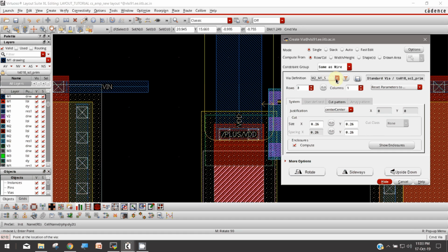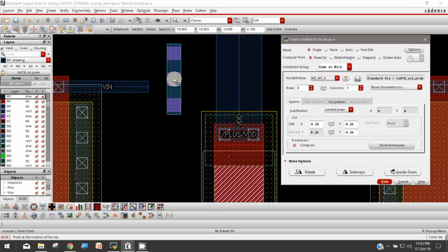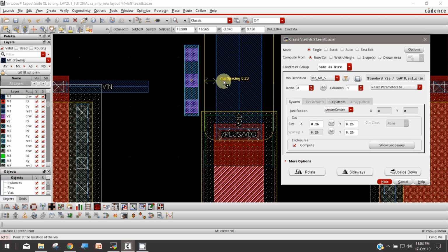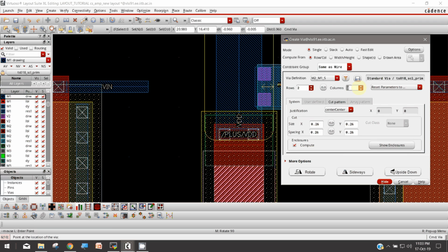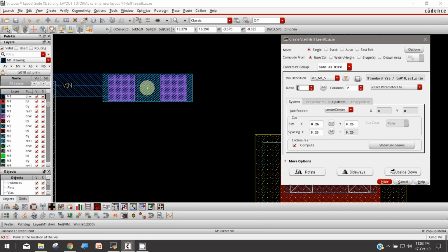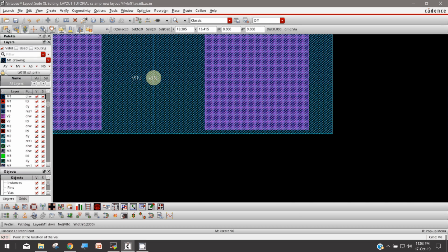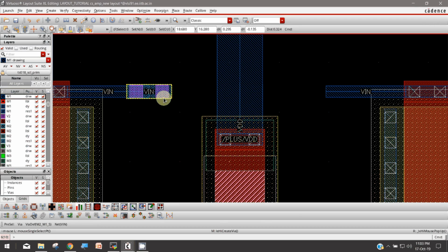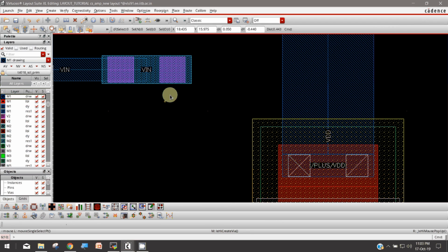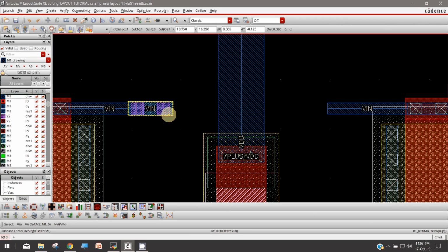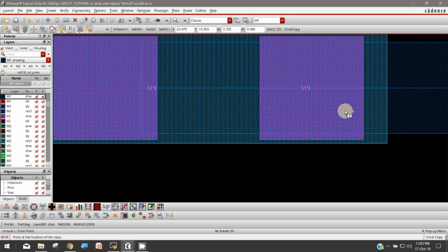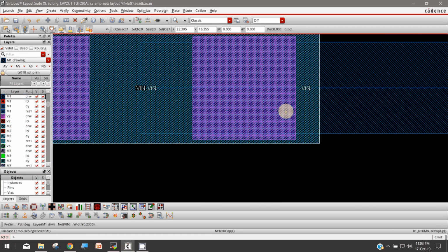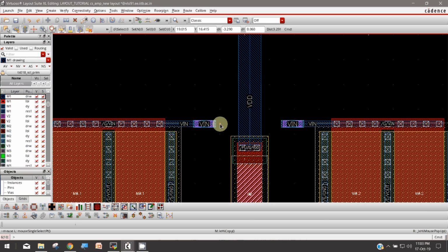So what I will do is I'll create a via. So I'll select the metal layers. I need metal 2 to metal 1. Now as you can see, this is a 3-row 1-column via. So we can change the number of rows and columns in it like this. Suppose I want it like this. See here. Now a very good approach in analog layout design is copying things. So just copy this via and place it here. Even you can also copy connections, MOSFETs, everything you want you can copy.